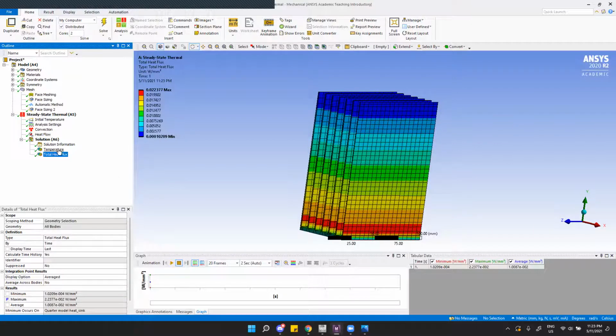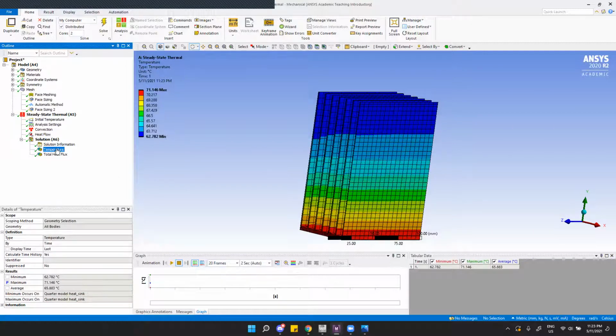The preliminary results are currently showing a promising trend. It clearly matches how a heatsink should perform when under thermal load. It also shows that the temperature matches with what is recommended online. As you can see here, the base is at around 70 degrees and the tips of the fins are around 60. The online trends recommend maximum temperature ranges between 80 degrees and 90 degrees.